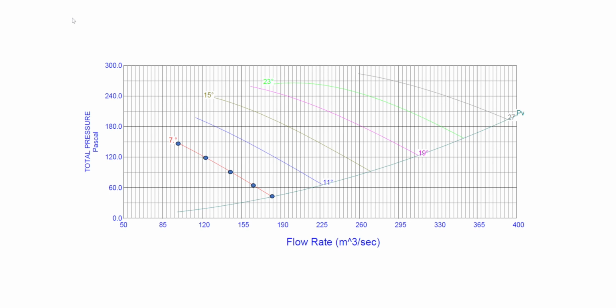Now the purpose then is to get all of these curves into the cooling tower software. Now what you need to do, and it depends on the shape of the curve, you have to identify a couple of values on the curve, and then we're going to use these values to fit the curve through the data.